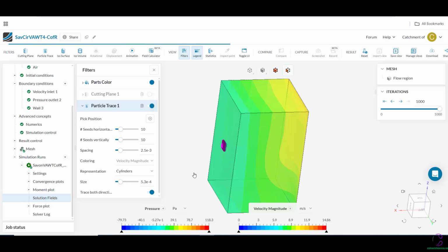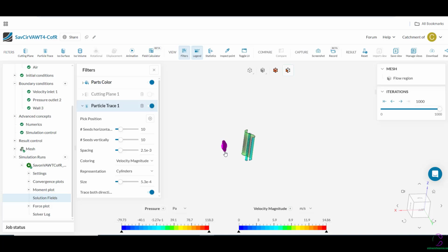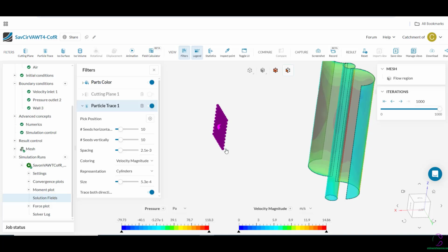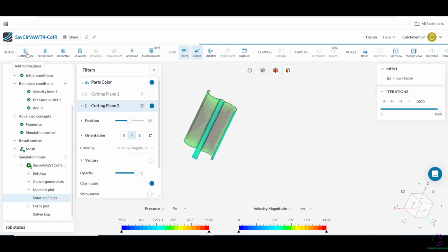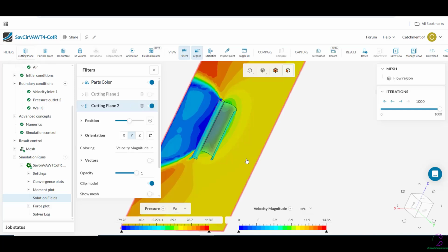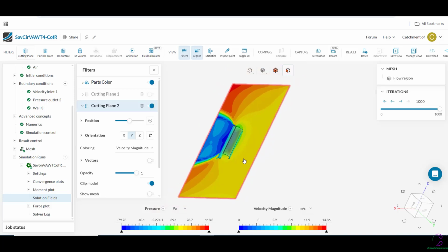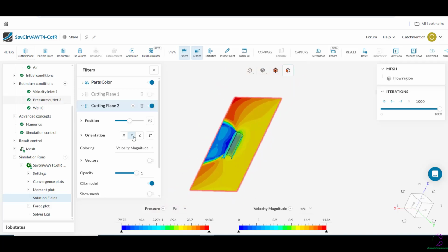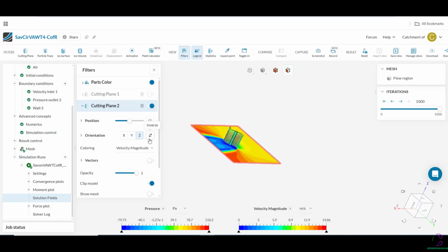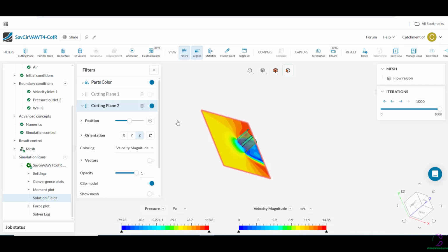You can see it's not showing any airflow around the wind turbine system. When I checked with the cross-sectional pressures, that's when I realized that the wind speed was dropping before the wind turbine system. Hence, it confirmed that the orientation of the wind turbine system was not what was expected, meaning that the inlet was on the other side. So it was switched back, and then the particle tracing was tried again, in which case you'll be able to see the outcome.